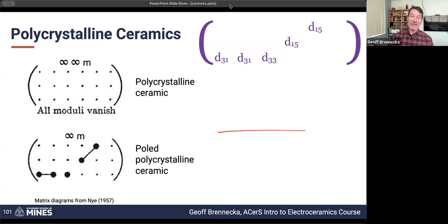Aluminum nitride itself, until recently, was considered the prototype piezoelectric that is not ferroelectric. And in 2019, some colleagues in Germany showed that once you modify aluminum nitride with scandium nitride, you can actually get it to switch. But the coercive fields are enormous.